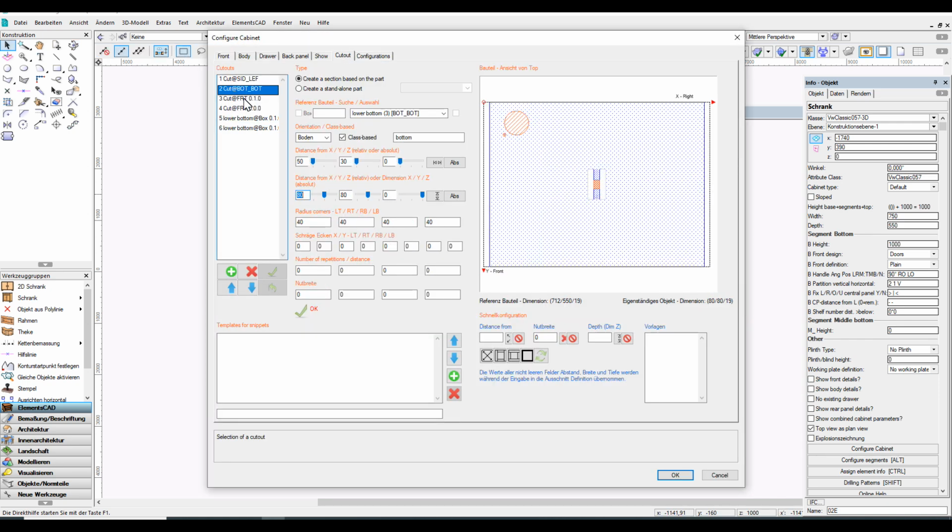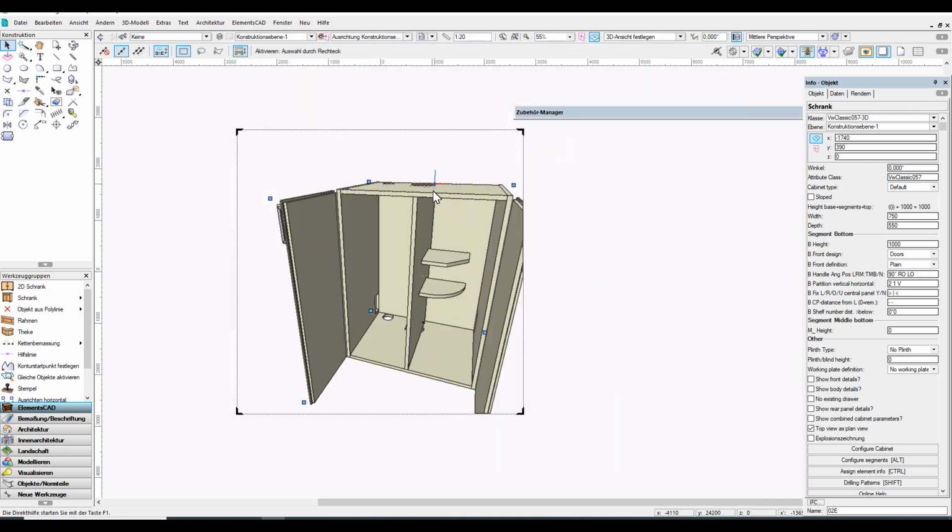But of course you can combine the cutouts. So when you have a cutout, let's change the position and make a larger distance with 300 millimeters, and here we have 100 millimeters, and now I want a further cutout, and here I don't have any radius, and now I can change the position and subtract, let's say, 50 millimeters, and so here we have the new contour.